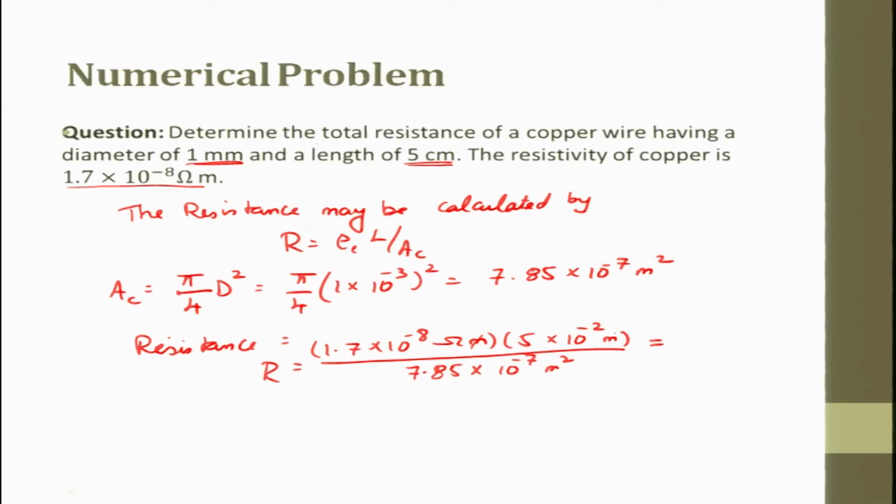So, this is nothing but 1.08 into 10 to the power minus 3 ohms. This is the resistance built up in this problem. The resistivity of copper is given because it is known. If you see very clearly, this is a material property, whereas this is a design or intentionally manufactured thing. So, now using all these things, the total resistance has to be measured.